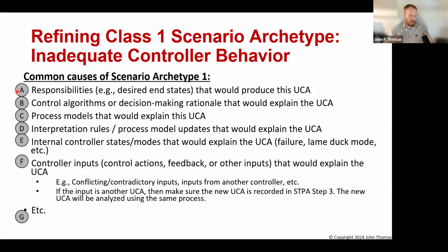But it was sort of inferred and assumed by the engineers that that trumps everything else. If it's an invalid state transition, I don't care if it's going to cause mayhem, I'm going to just stop the entire machine. And that's interesting. Probably a different decision should have been made. The responsibility probably was to ensure safe states. If it's invalid or not, let's not just shut everything down. Let's make sure it goes to a safe state. Anyway, that was a tangent.